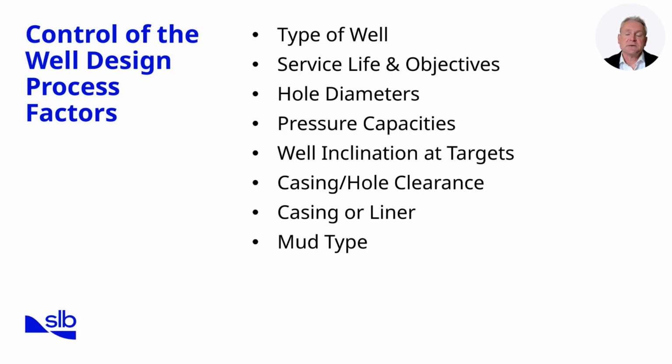Pressure capacities must be defined, ensuring casing and fluids can manage formation and reservoir pressures safely. Similarly, the well inclination at targets dictates how the reservoir is accessed, influencing recovery efficiency. We also control casing to hole clearance, which affects cementing success and completion options.